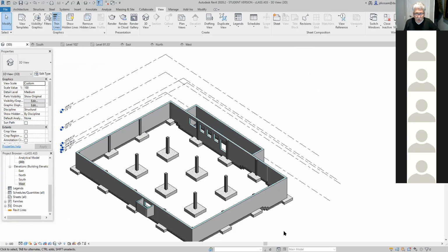The two last things we need to put in to complete the elements we want to put in are those beams. Remember that there's beams here, across here, okay? And if you look at section FF, that gives you the size of the beam. And if you look at the plan view, where the south wall is, it shows you where FF and FF are. In other words, you have a beam on axis 3 and you have a beam on axis 4.